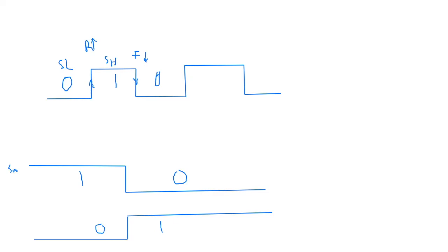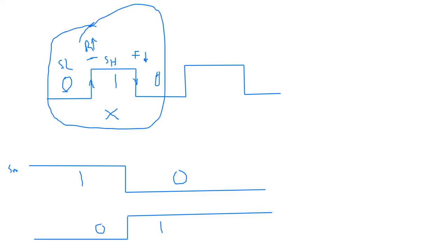So we've got the stable state low, and we've got the stable state high if we want, but we may not actually use this. And we've got the rising edge, we've got a falling edge, or we can say any change at all, it should respond. So as soon as I make a change, it responds. And we are referring to the external interrupt, or whatever signal is generating the external interrupt. In this case, we can use a switch as an example. I hope you understand that.